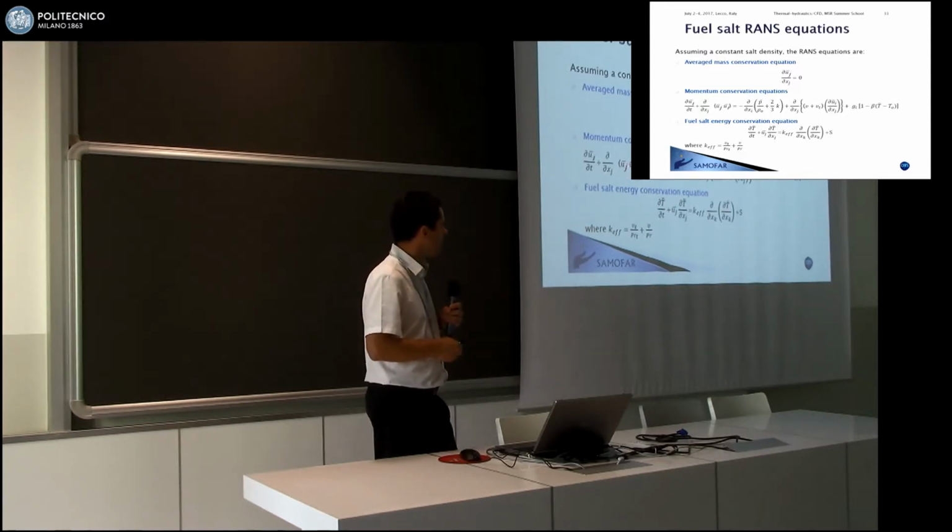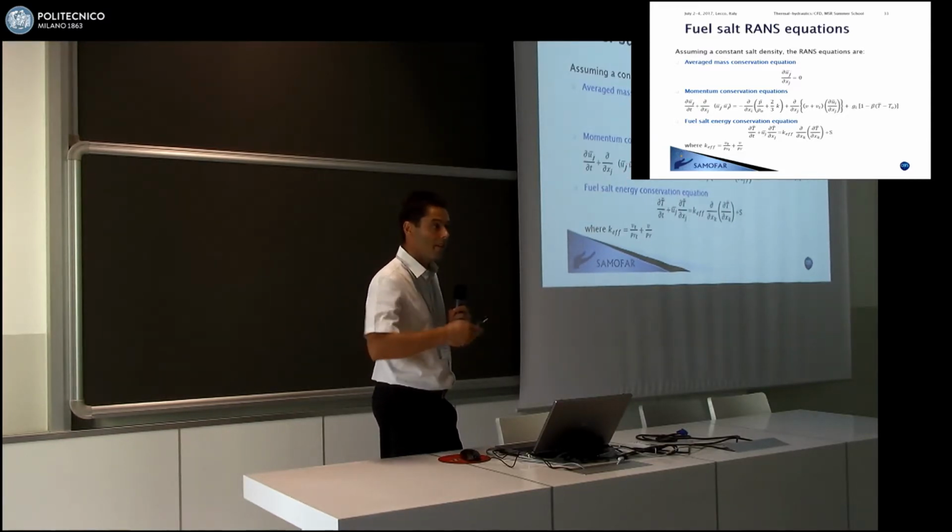These equations provide information about the average value of the properties of the fluid, like velocity, temperature, pressure, and so on. And these equations are a little bit simpler to solve, and they do not require a mesh that is at, I would say, micrometers of length. Of course, there are some issues, like you need to know the turbulent viscosity and the turbulent diffusivity, and you will need to use closure equations for those particular things.